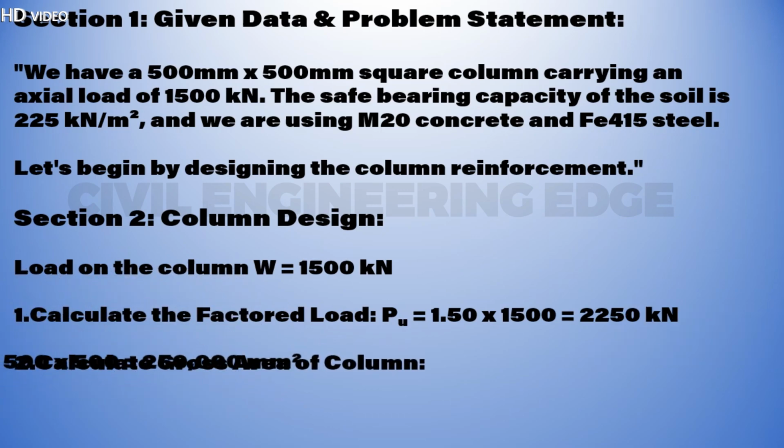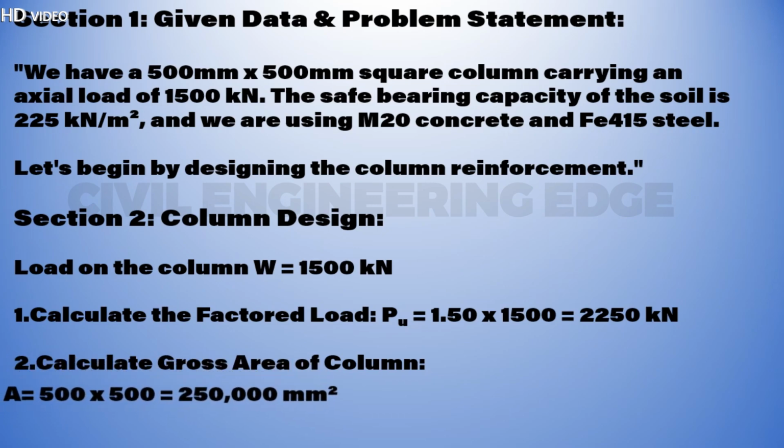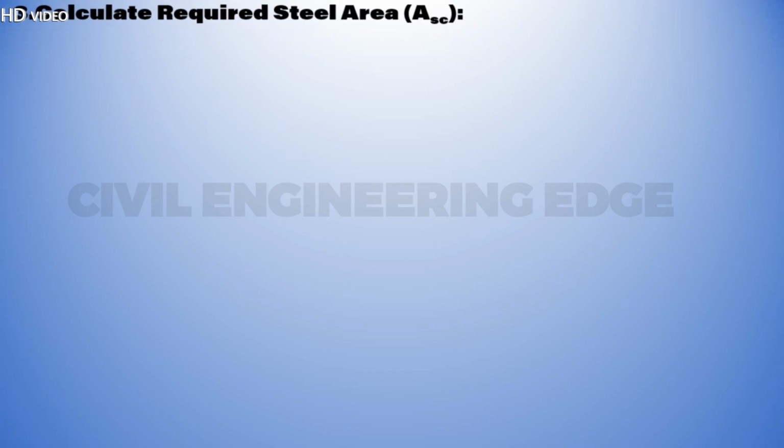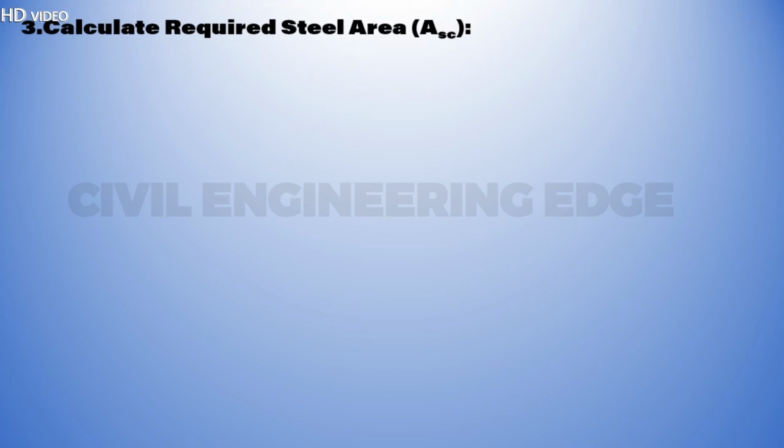Asc equals 925.75 square millimeter. Provide 4 bars of 20 millimeters diameter, 1256 mm2.